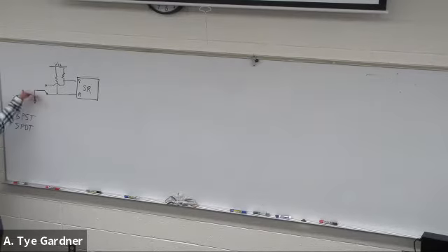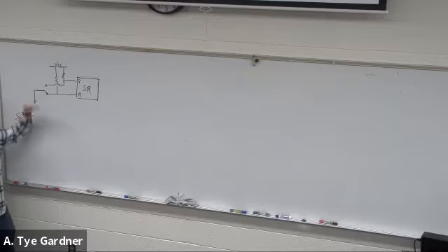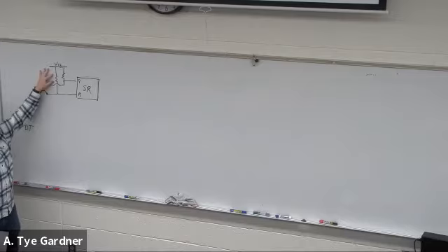Okay, so it is either connected to reset or set, which is ground. But there is a pull-up resistor that is making sure that it behaves a little bit better. So let's say my default position is reset. So I'm defaulting to 0. And if I push this button, it's going to throw it to the set position. Now, what's nice about this is we're pulling up weakly. We're using like 10K resistors here, something pretty big.